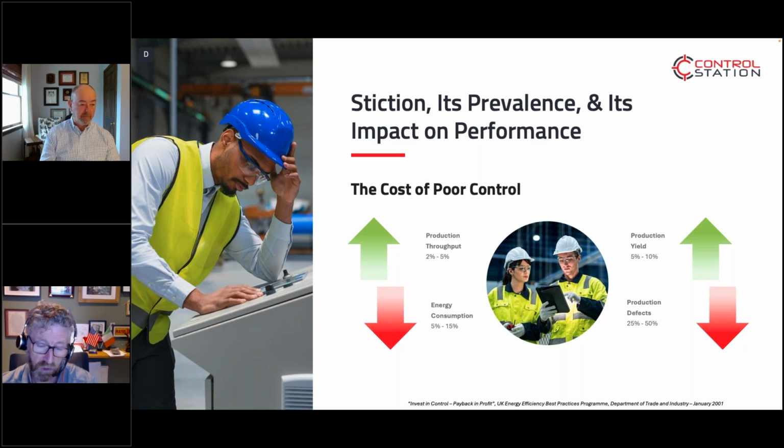and it probably runs to 2.25 boilers running, or there's an increased floating reserve in some of those. And defects, again, that's from that poor set point management, variability causing not perfect product being produced. With this popping movement of the valve up and down and up and down, it's highly unlikely that the valve is ever going to settle at exactly the right place to hold set point.